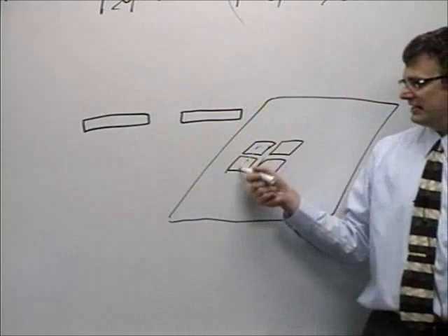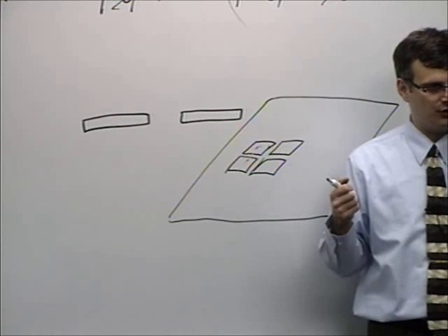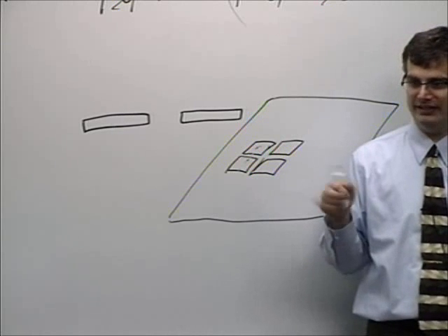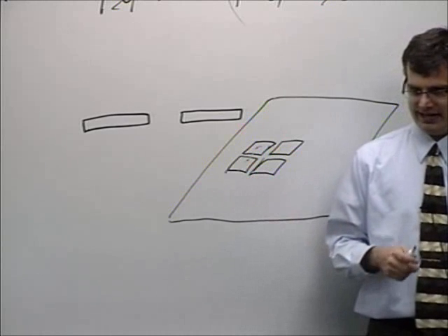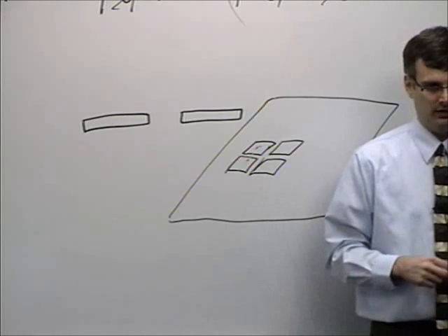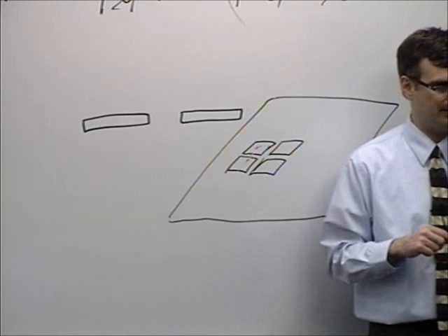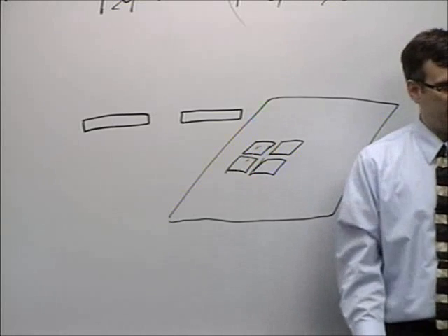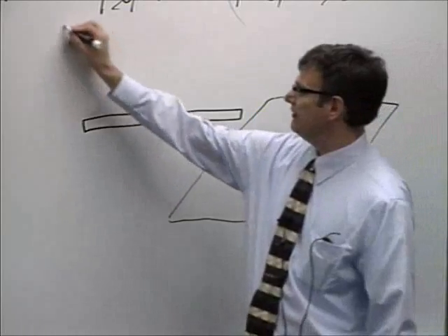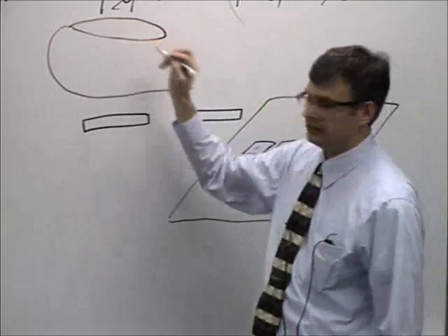Now, of course, these can't interfere with the screen itself, so they make this out of a special conductor. Usually it's indium tin oxide, ITO in the industry lingo. And it is optically transparent, but it conducts at DC pretty well, which usually those two things are mutually exclusive. It's actually very hard to find a substance that behaves like that. So you can see through it. It's invisible.